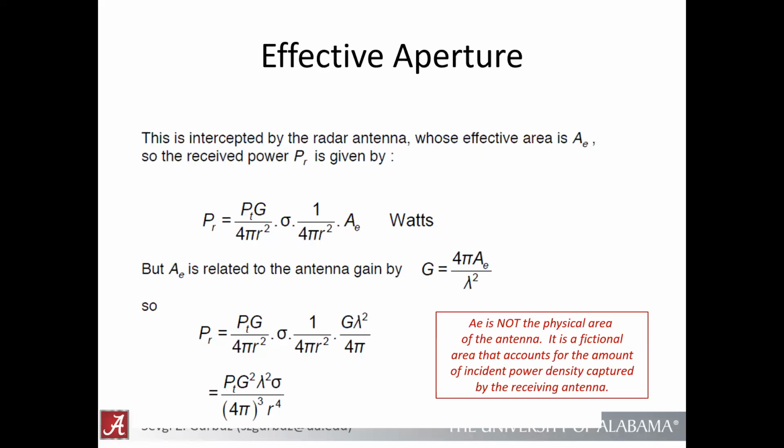Once we get the backscattered signal back to our radar transceiver, the next question is how much of this backscattered energy is actually being acquired by the radar antenna. The way we can consider this is by defining a parameter known as the effective area, which tells you the ratio of the actual power being acquired by the antenna. There is a design rule, which I do have a derivation of, and I can show you where it comes from, independent of this tutorial.